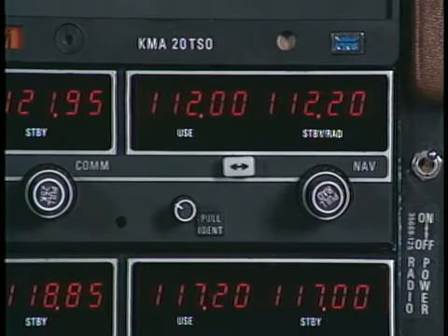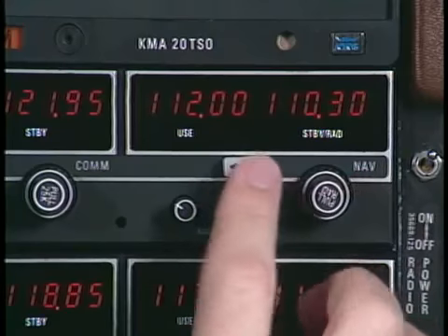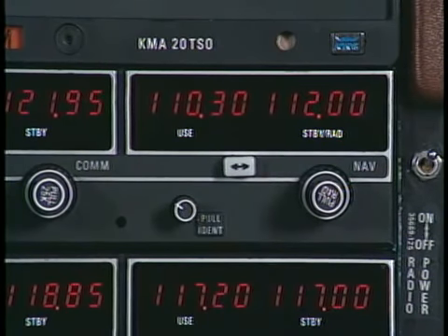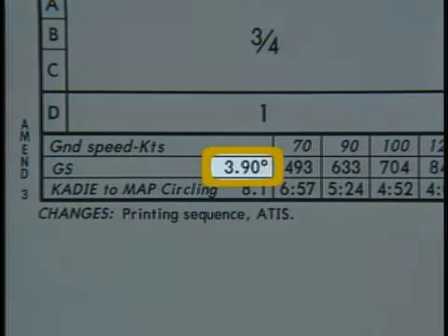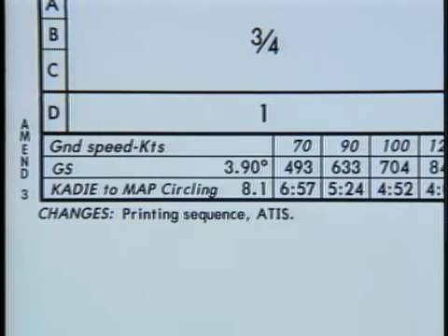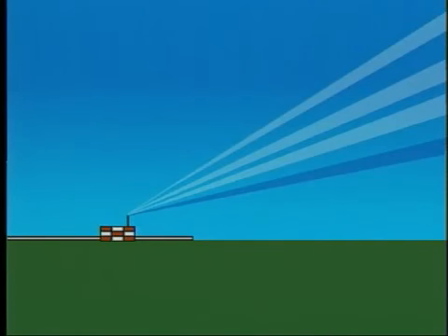The transmitter operates on a UHF frequency, which is paired to the associated VHF frequency. When you select the localizer, you automatically select the associated glide slope. The center line of the glide slope is usually adjusted to an angle of 3 degrees above horizontal. However, this angle may vary slightly due to local conditions. False signals can also be generated at high angles. This usually isn't a problem if you intercept the glide slope at or near the altitude and position prescribed on the approach chart.